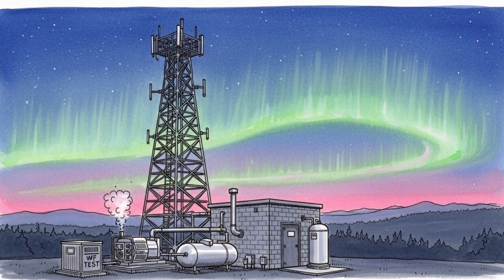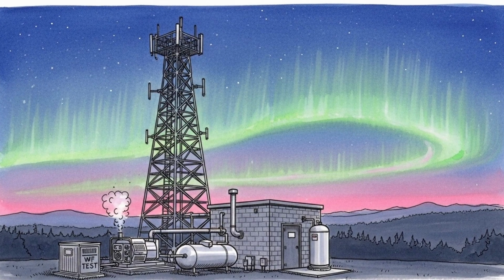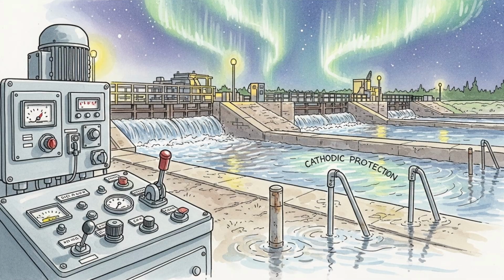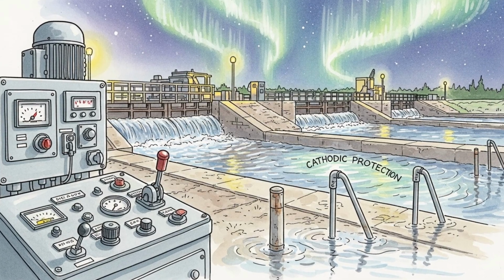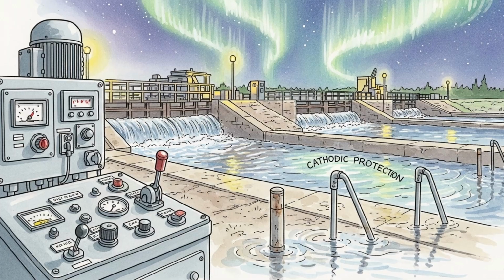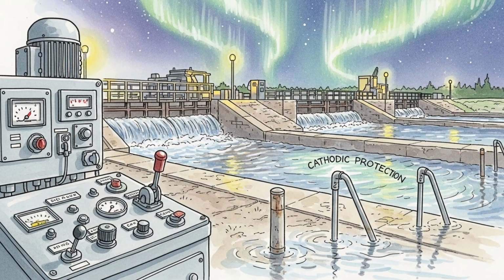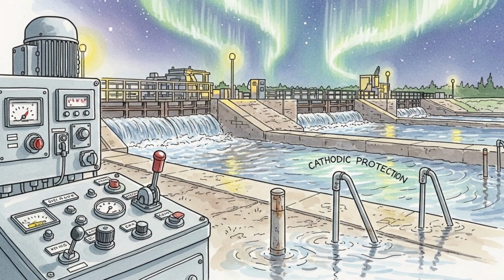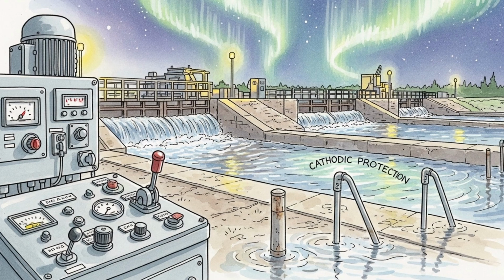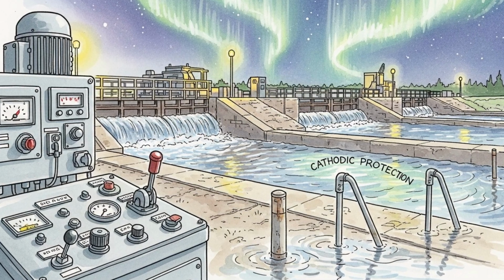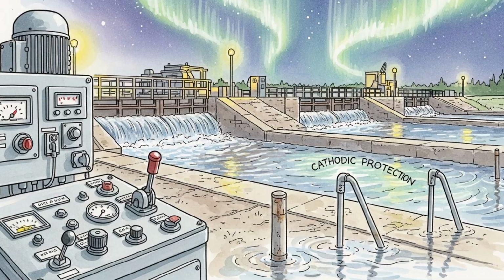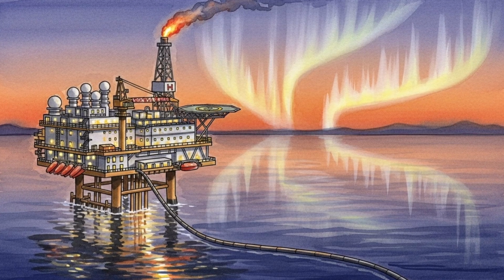Facilities reduce exposure by isolating timing from the public internet, using local primary references, testing holdover, and checking that automatic failover works between time sources. They verify grounding, cable shields, and surge protection at cabinets that connect long field lines. Operational practice ties measurements to actions.